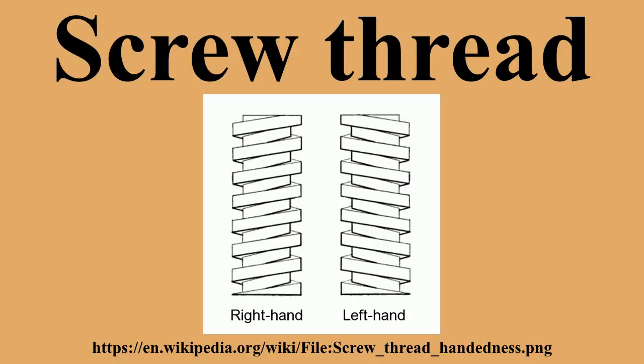We have assumed that the flanks have the proper shape, angle, and pitch for the specified thread standard. It is generally unrelated to the major and minor diameters, especially if the crest and root truncations of the sharp V form at these diameters are unknown, everything else being ideal. D2, D, and D1 together would fully describe the thread form.